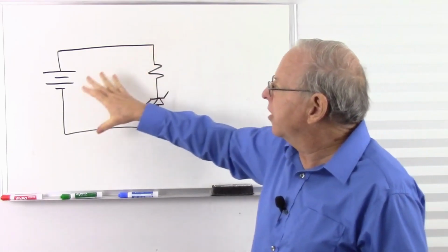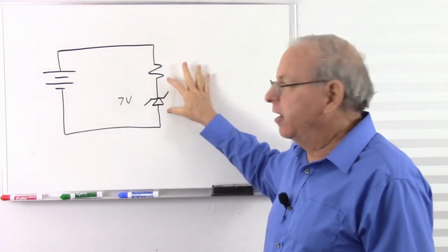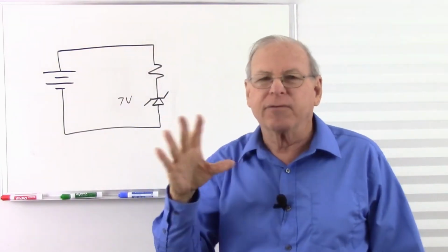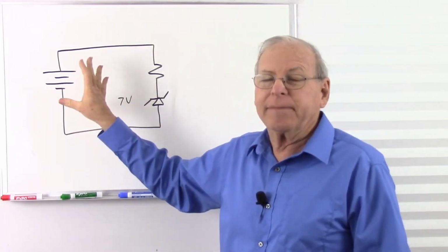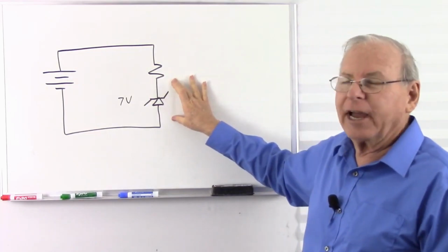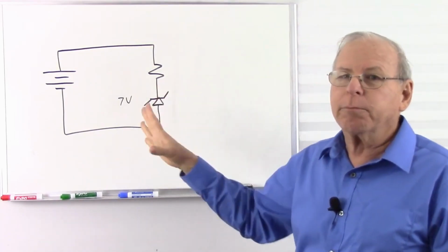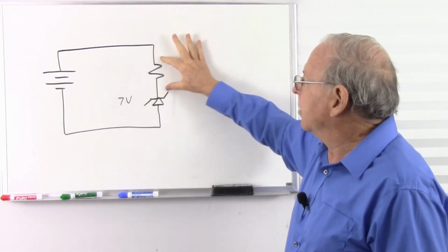But you'll see it's necessary because otherwise you can't get a voltage across the Zener diode other than the battery voltage, not counting internal resistance. But essentially, whatever voltage the battery has is what's going to be across the Zener diode. And when it gets to its operating region, it's just going to cascade out and burn up. And so we need something here.